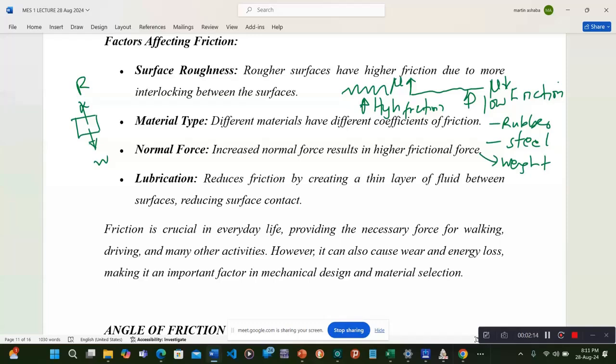In other words, as this body is trying to push on top of the table, the table is trying to push the object above. And at equilibrium, that's why you'll never see any motion, that the object has moved up or has moved down, because these two forces are equal. So that is the normal reaction. The weight of the body produces the normal reaction.